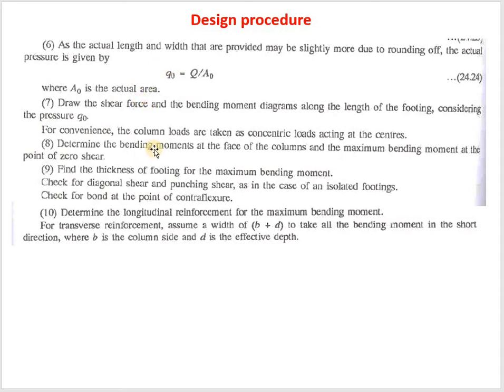So for that particular pressure and the loading, you will be finding the bending moment and shear force, and always the thickness is designed for the maximum bending moment. So thickness of footing is designed for the maximum bending moment, and also you find the position where there is maximum bending moment, and for that you will be designing the longitudinal reinforcement, and also you will find the bending moment in the short direction to provide the transverse reinforcement. So you need not go into too much detail. This detailing portion is not there. Usually the questions are asked only to find the dimensions of the foundation.